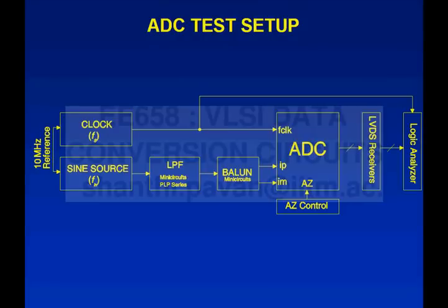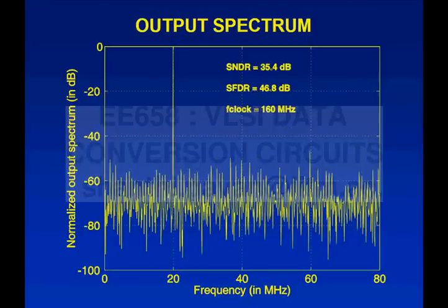And then we have some knobs to play with. You can run AUTOZERO whenever you want, okay? And we could disable AUTOZERO for a long time if we wanted to figure out how long it would take before the ADC would get screwed up because of leakage from the capacitors and so on. This is the logic analyzer, and then you do the FFT from the data grabbed from the logic analyzer.